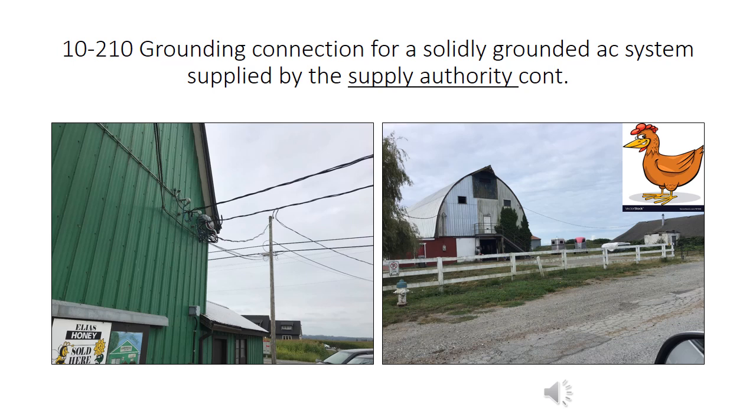Except for buildings housing livestock, prior editions of the code permitted regrounding at an outbuilding. Not anymore. In these examples, any outbuilding cannot be regrounded, and a separate bonding conductor must be installed with the feeder conductors. This is not an issue if TEC or ACWU is installed underground because a bonding conductor is integral with the cable. Neutral support cable, however, poses a problem in this situation.